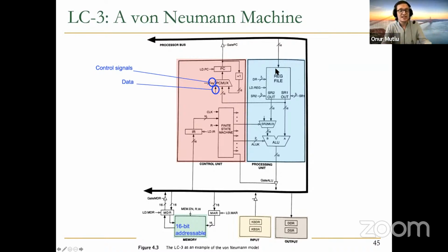So the machine itself needs to provide the data paths and the control paths so that you can actually take a data value, take an address produced somewhere over here, put it onto the bus, place it into the MAR, and then interrogate memory with it using the right control signals to memory. And then the memory responds into the MDR.